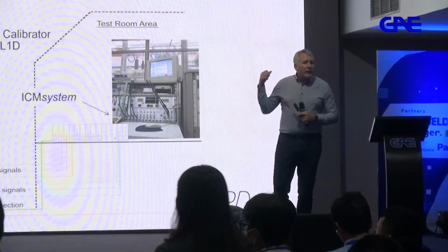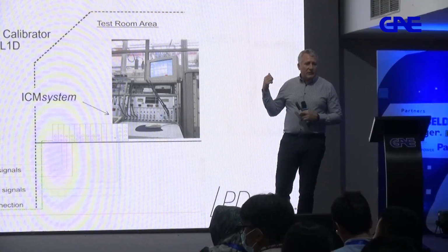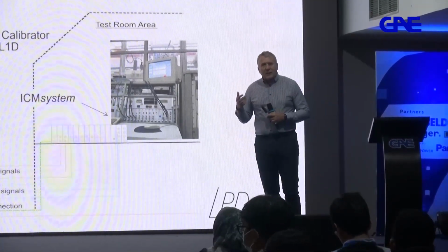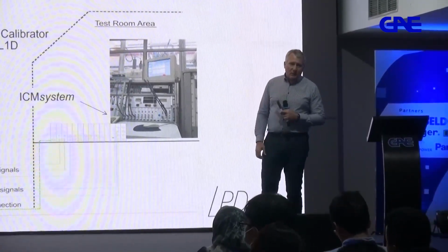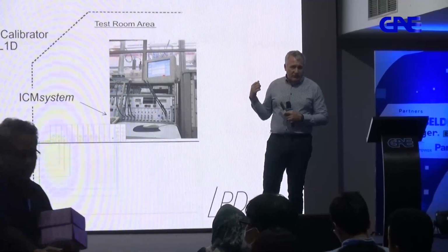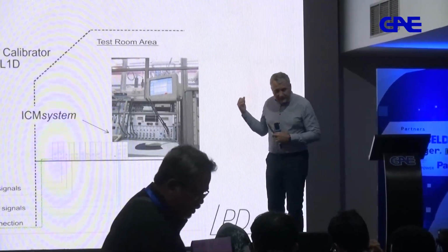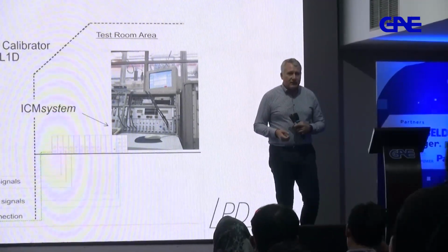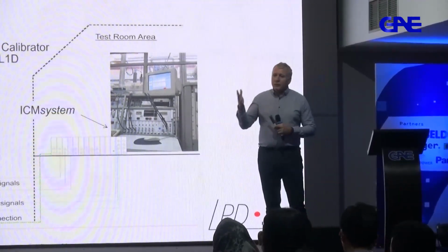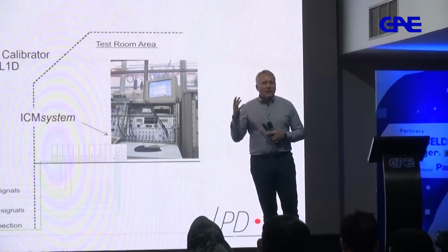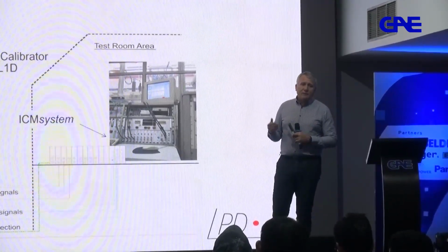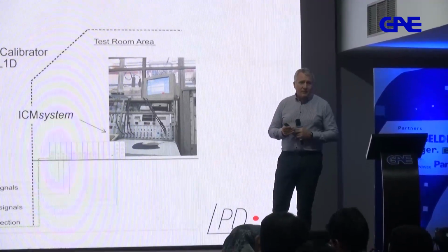So without looking at the values of partial discharge when you produce a transformer, without looking at the patterns, you will never know what kind of test object you got. So it's a very important test. It's a very important standard, this IEC 60270, and it's very important for all of you power utility people who are commercializing such transformers to ask for those test reports.